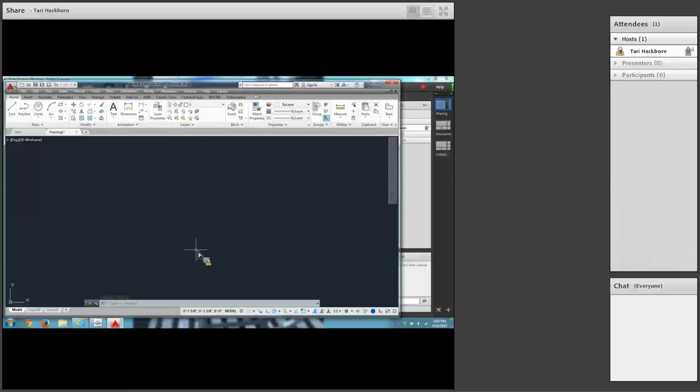Now you have a small building that is 35 feet wide, and that's not going to fit in this drawing area, is it? Because this drawing area is 12 inches by 9 inches. So type the word limits. I like the lower left corner at 0, 0. That keeps my origin down here in the left. So just press enter.